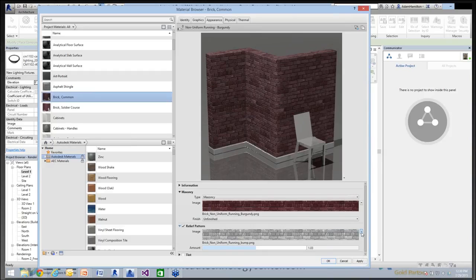There's also the ability to, if you don't want to use an image, use this little drop-down button on the right and use a non-standard bump. If you're using tile, this will give you the grout lines. It can be used for brick as well if you set the sizes correctly to get the offsets.